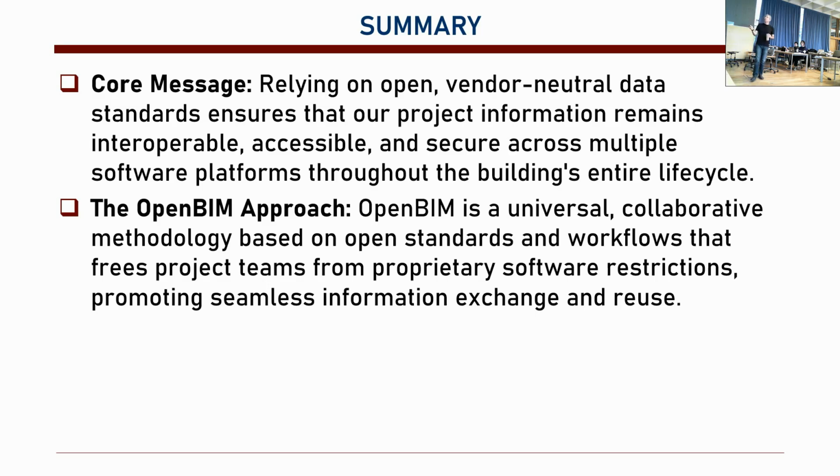Okay? So the OpenBIM approach is basically a universal collaborative methodology. So OpenBIM is not IFC. IFC is one of the parts of OpenBIM. But ISO 19650, which you are learning this semester, is OpenBIM too. So it's a standard way of working based on the International Organization for Standardization. Okay? So we basically say that, well, I will create building information like that, with all these agreements between people, parties, descriptions, etc.